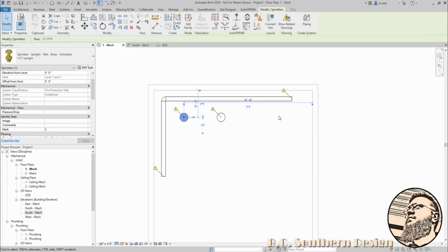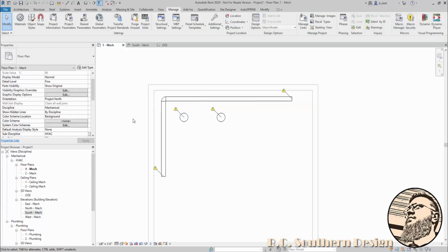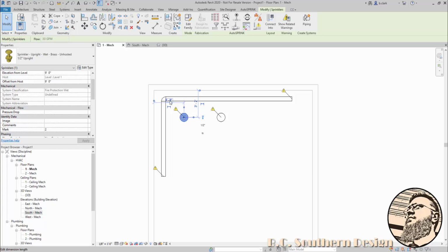So it's going to move whatever it is you have selected, and I use it regularly with sprinkler heads. Now with the sprinkler head, you can see it reached all the way over here. This is the minor annoyance. You can of course just simply move it over, and whenever you have the faces set, it's going to prefer to automatically snap. You have to use Tab to get to the center of the wall if that's what you wanted, but then you can use this to get yourself a good starting place for a sprinkler head. We'll say 3 feet.